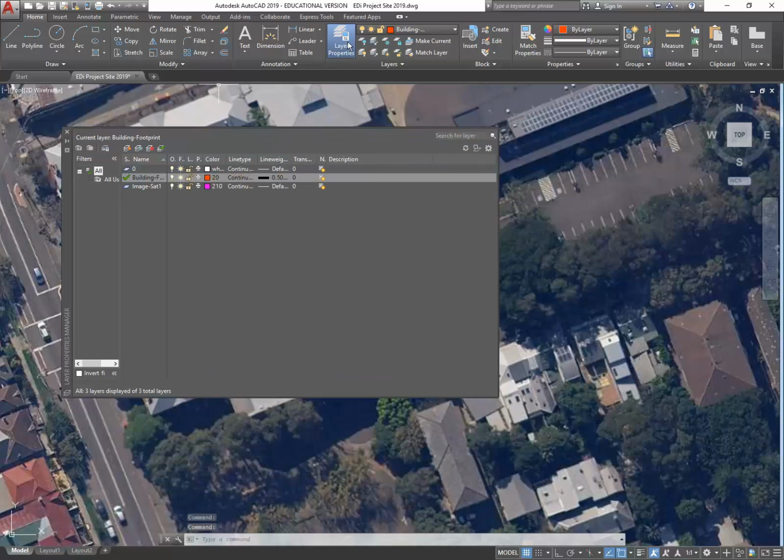Yeah, now it's a great thing, because if you're using that and you're using your line weights and your layers, you don't have to worry about those annoying standard colours. You know how people have these fixed colours for layers? That's a really old thing, and you haven't had to do that for 20 years. But I know a lot of people still are in the habit of doing it because they don't use this one enough. So, yeah, it's good that you noticed that.